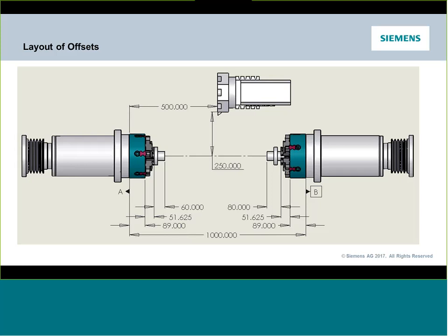So our datum A, which would be our main spindle face, that's where all of our dimension data is going to come from. The first thing I see is our 1,000 millimeters. What that's going to be treated as throughout our part programming scenario is the retract position or safety position we send the sub spindle back to. So that'll be where it goes at the start of the program. It'll be where it goes back to when I go to start doing some machining. Now that could be the max travel of Z2, but it doesn't have to be. It's just important when you come up with a plan of how you're going to use this machine and where you want things to move to, that you give yourself a known location that you can work from.